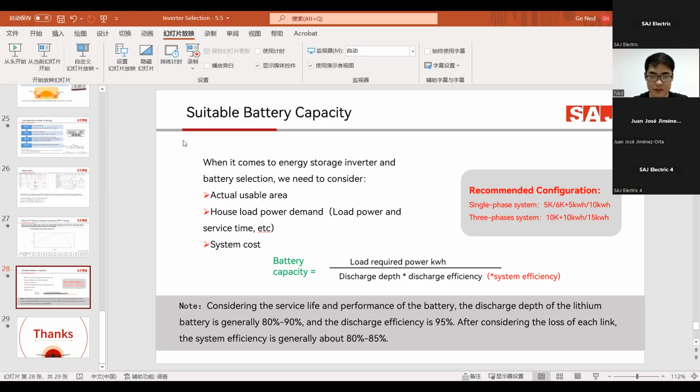But in self-using mode, it will take about 13 days to fully charge, if 3 kilowatt hours are generated for 4 hours per day for battery charging. That is a waste of battery investment.